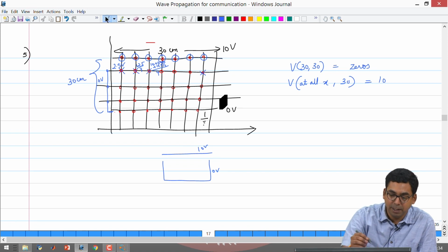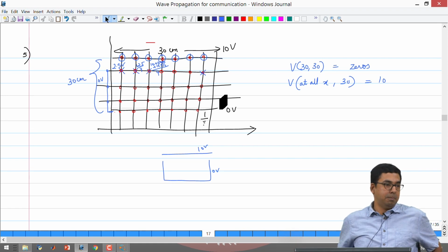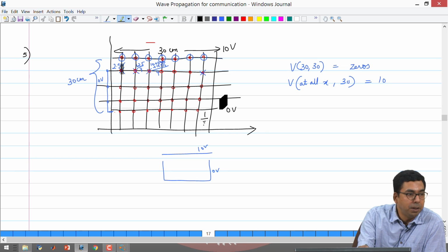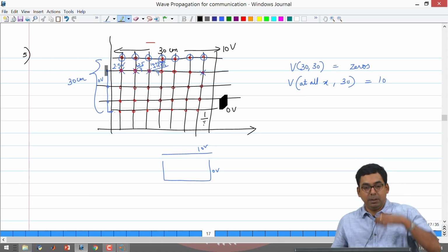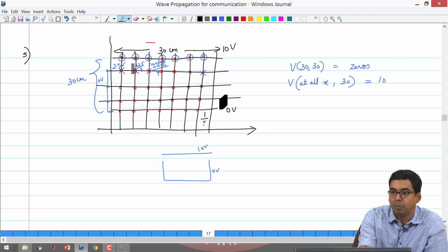Now, one of the things that we can do is relook at how else I can treat this boundary. So, we will start with the first point again. I have this value, say currently unknown, and I have 3 points present. The fourth point, on the left hand side of this particular place where I want to calculate the voltage, is not present. One of the ways to think about it is, suppose I have an unknown value of the voltage here. I can make that value equal to the value on the right hand side, that is, I am going to have something like a mirror image of what this voltage is going to be.